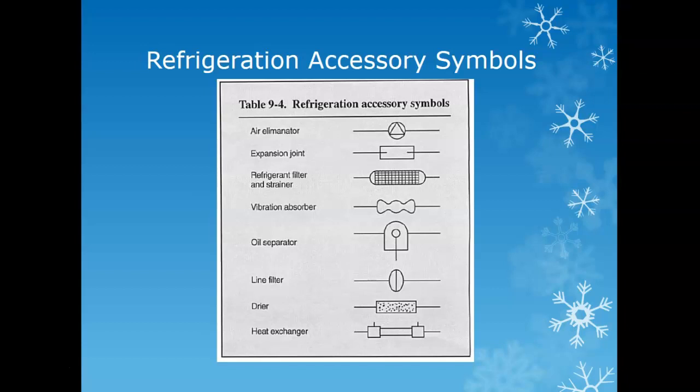Where the water line connects to the wall, there's a little valve that you can turn on and off to turn the water off to your toilet. A little fragment of metal about yay big had gotten caught in that valve and broke it. Just a little piece of metal. Random piece of metal, nobody knew where it came from, nobody knew how it got in there. It does not take much for random things to find their way into your pipes. So it is always a good idea to have a filter or strainer of some sort to help deal with it.